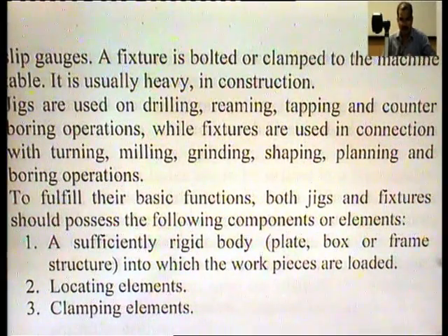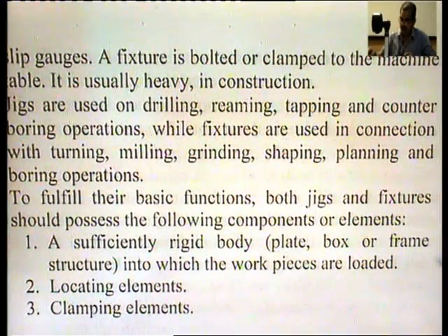Secondly, it must have locating elements, so that a job can be located or its movement can be constrained or restrained in particular directions. Then clamping elements. Clamping elements are used when locating elements are unable to locate the job or workpiece. In that condition, clamping elements are used.